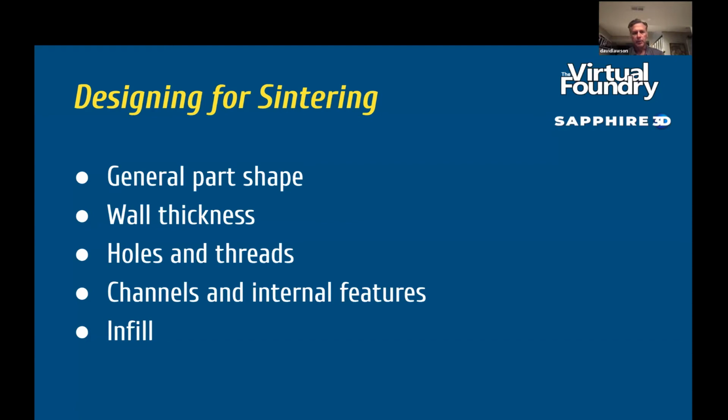Yeah, and that's pretty typical even of machining processes. My background had been in injection molding, and when they're designing injection mold tooling, there would pretty much always be an iteration process. What I found with this material and the design of it and printing and sintering, especially on smaller parts, is I can get to where I need to be in about 3 tries. And then as long as I follow the process consistently, it's very repeatable.